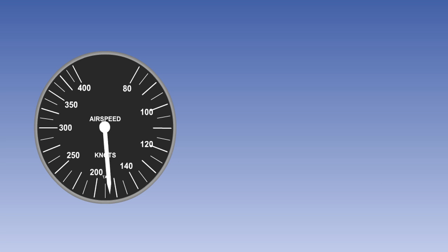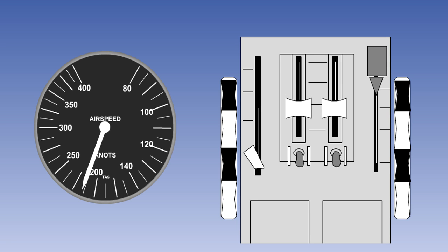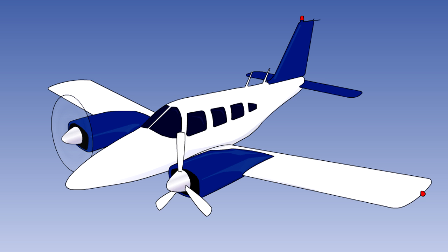The aircraft will need to be trimmed in pitch as a result of changes of speed, changes of power, or varying centre of gravity positions. Trimming in yaw will be needed on a multi-engine aircraft if there is asymmetric power, or on a single-engine aircraft as a result of changes in propeller torque. Trimming in roll is less likely to be needed, but could be required if there is asymmetric power or if there is a lateral displacement of the centre of gravity.